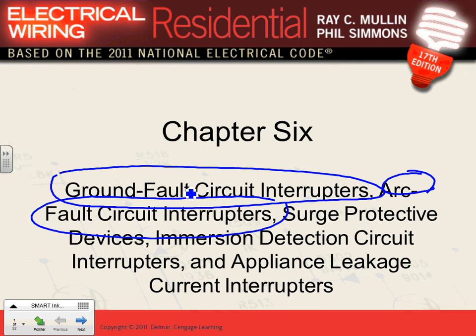So that's one of the reasons, Aaron, that we have boxes in the electrical industry. We put things in termination boxes. But the problem is the extension cords that you have right here in front of you. Imagine in every house in America, extension cords are all over. You pull and push things over them, you abuse them. So if they get frayed and they're plugged in, they could arc. You could have a line series arc or parallel arc.